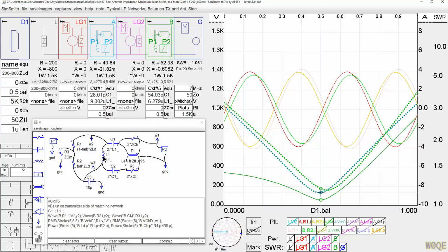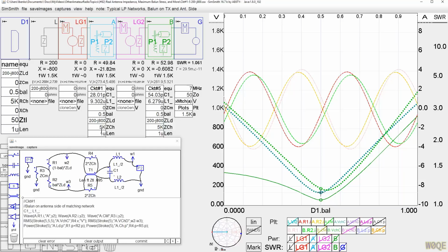Also, if you want a low-pass topology here, you're going to be stuck with two roller inductors, perhaps, or a more complicated circuit. In my opinion, it's really not worth trying to put the balun on the transmitter side generally, but balancing the circuit before, so going to this circuit with a balanced network and a much smaller common mode choke for a balun is very appealing.